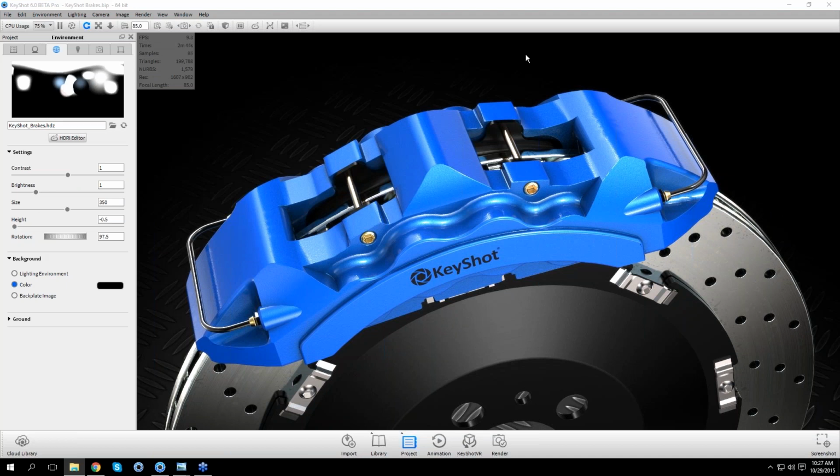We just had a question from Steve. Yes, I believe I just answered that. You can save out that image pin as an HDR or EXR, and that will preserve the gamma and all the lighting information that you find in a 32-bit image. So when using image pins in the HDRI editor, I do recommend using a 32-bit format. HDR, EXR works the best.